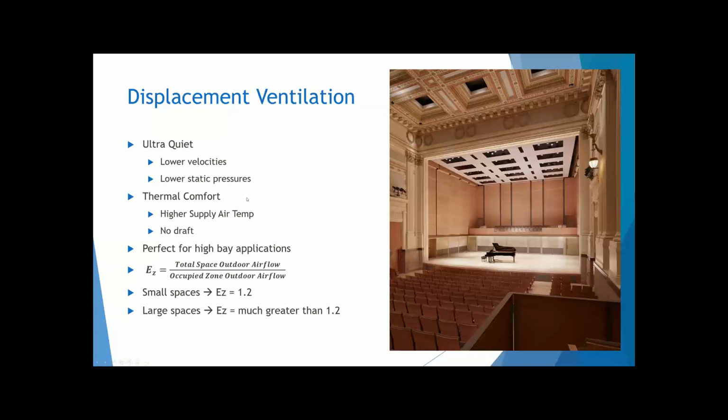And then also the thermal comfort that comes along with a higher supply air temperature is much better, considering you're not going to be feeling a 55-degree air temperature at any point. Normally that 55-degree air temperature in a mixed system would have mixed a bit anyways, but you're supplying a much higher temperature, so it wouldn't be uncomfortable and there wouldn't be a draft because it's not going fast at all. So it's a much better thermal comfort as well. So this is really great for high bay applications,